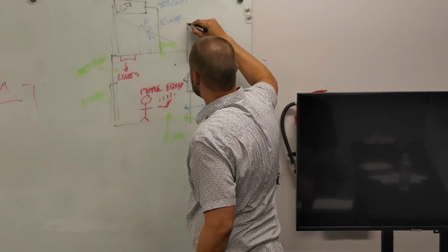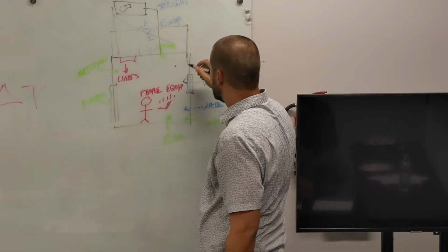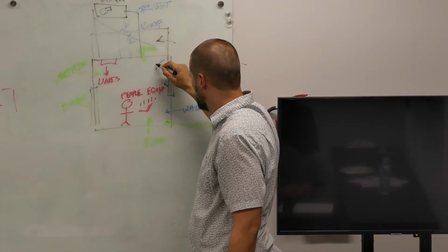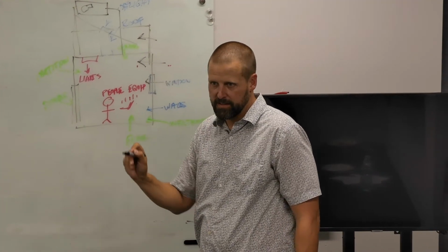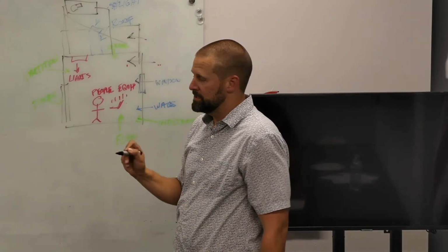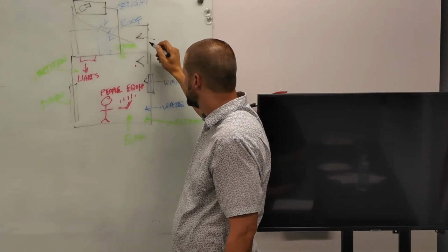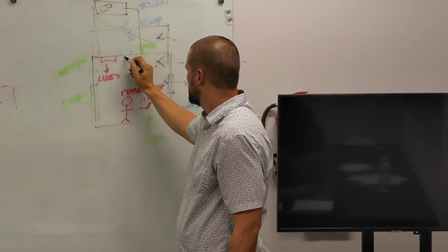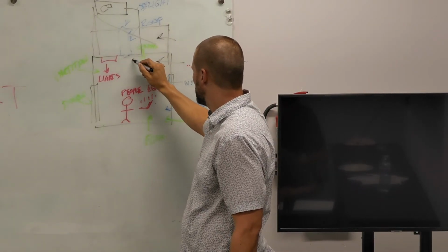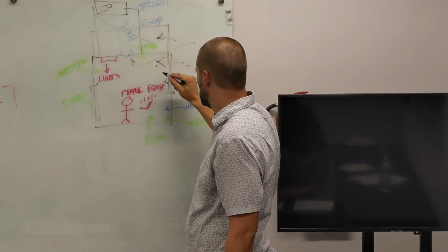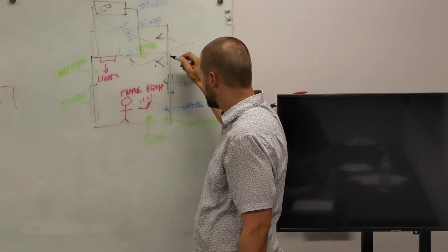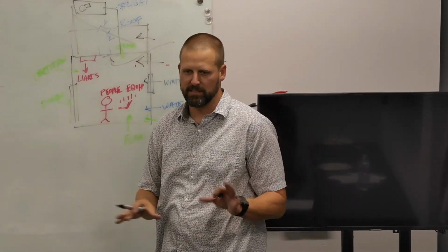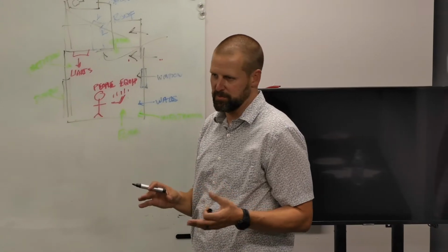If this wall goes up, some of this wall load is going to go to the ceiling space, and some of this wall load is going to go to the space. Generally, what that means is we will calculate the airflow for this diffuser to cover this space and the wall load for this space. Practically, whether we do this or not is another discussion, or whether it really matters.